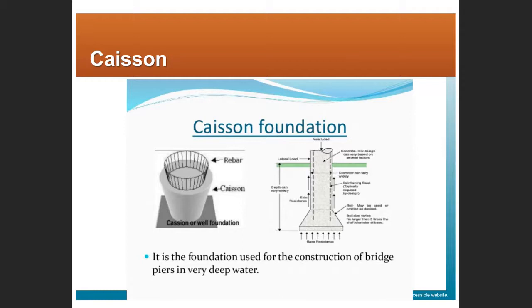Right? So caissons may be used in building construction. Certainly if we're building a high rise, we'd be using caissons. If we're doing bridges or other sorts of things, we'd be using caisson type foundations. You see, in some cases, the bottom of the caisson gets wider at the bottom. That's called the bell. So the bell would be wider to give us more surface area bearing on that soil,